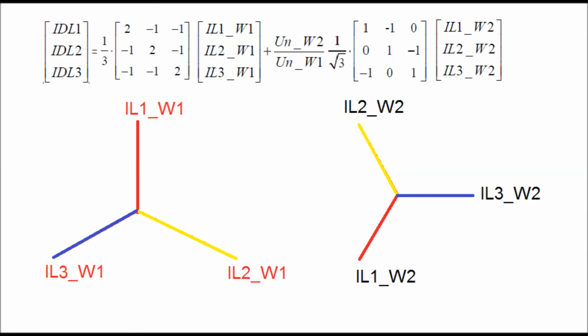degree. The reason is that in the HV side the current enters from the P1 to P2 direction in the CT primary side, but in the LV side, since it is a YN D1 type, there is a phase shift of 30 degree lag between the LV side current and HV side current. Due to the current flowing from the P2 to P1 direction, there is a further 180 degree phase shift in all the secondary side currents, and that is why the LV side current phasor is at 150 degree leading from that of the HV side current. Similarly for yellow phase and blue phase respectively.